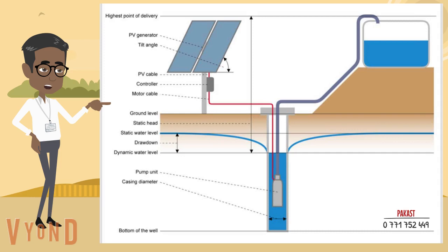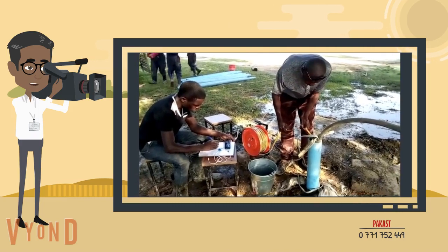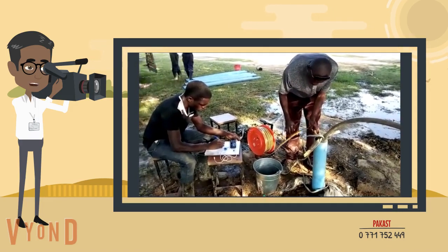Static level is the height of the water column in the absence of water intake. It depends on in situ pressure and it is established after downtime, as a rule, at least an hour. Dynamic level is the steady-state water level during water intake, that is, when the inflow of liquid is equal to the outflow. Column height is the difference between the borehole depth and the static level. Dynamic and static levels are measured in meters from the ground, and the height of the column from the bottom of the well. You can take measurements using a special tape measure, which signals when it comes into contact with water.